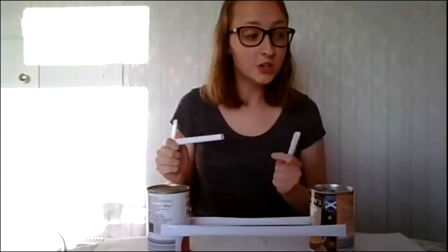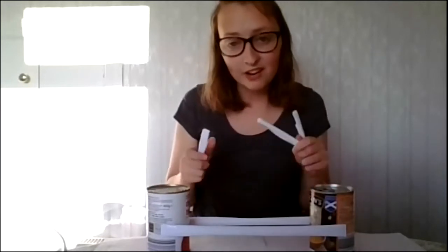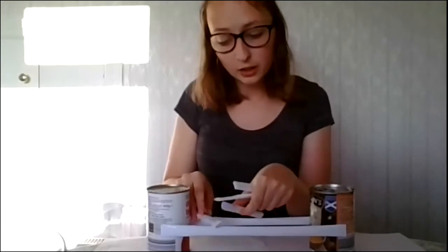So now we're going to use these to make a truss. A truss usually comes in triangular shapes, and we use them a lot in civil engineering. Trusses are great because they distribute weight over several different members. So instead of just on these 2, it distributes it across 6. And because they're triangular shapes, the load is distributed and changed into tension and compression. The deck truss stiffens the deck and stops the road from swaying, because that wouldn't be ideal if you're driving a car across it.